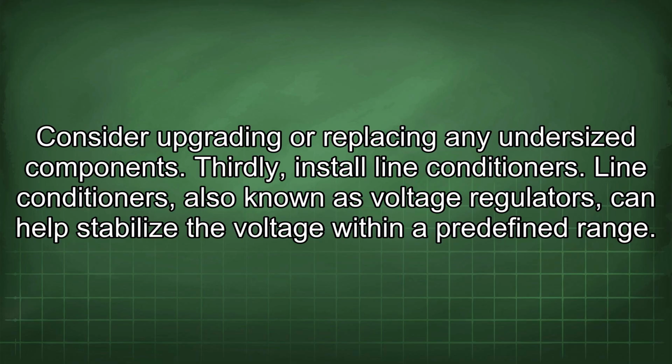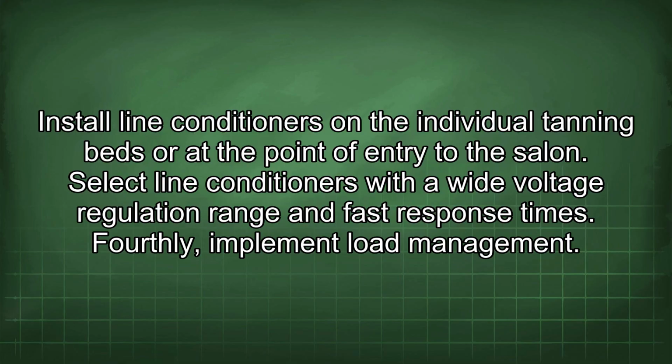Thirdly, install line conditioners. Line conditioners, also known as voltage regulators, can help stabilize the voltage within a predefined range. Install line conditioners on the individual tanning beds or at the point of entry to the salon. Select line conditioners with a wide voltage regulation range and fast response times.